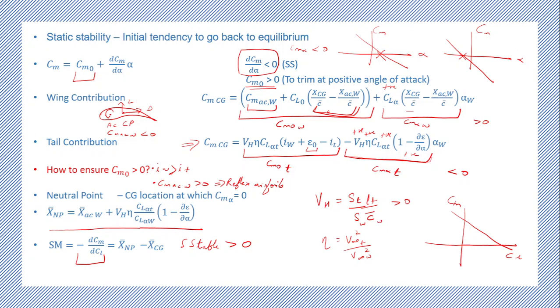That's what it means. So if I was flying at some 5 degrees and a gust comes and it becomes 5.1 degrees, the tail setting angle will not contribute in any way to bring it back or to take it away, right? The change in alpha, the d alpha, because of IT, there will be no change in d alpha, correct?